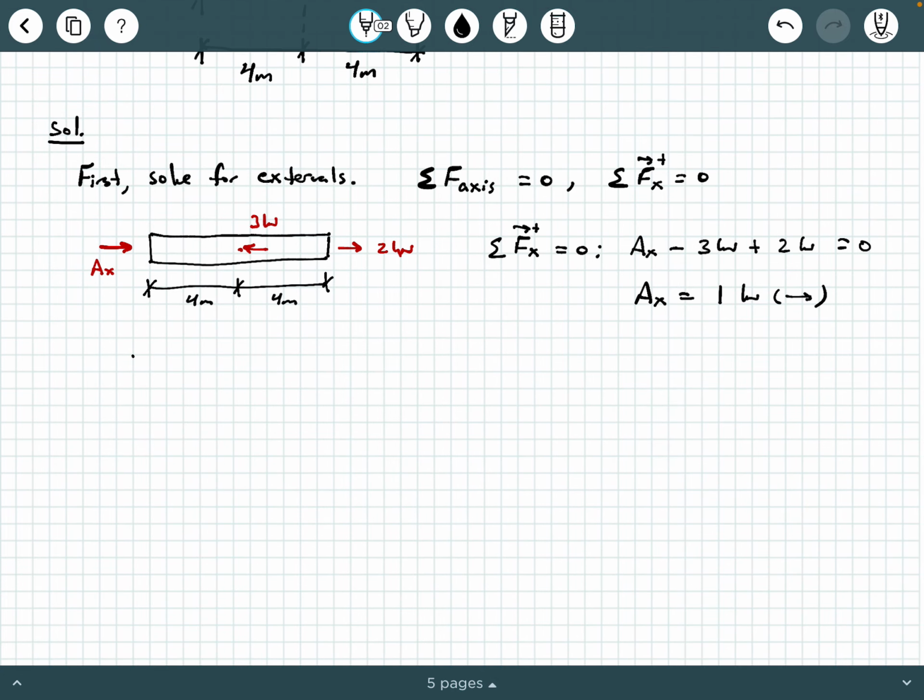Now we're ready to draw the axial force diagram. So if you remember, we're going to set up a set of axes. The vertical axis is going to be force, and the horizontal axis is going to be an x location. And what are our units? Well, the force units are kilonewtons, and the x units are in meters, okay? So what we're going to do here is we're going to put a sign convention with that force, okay? So up here on this axis, I'm going to say things pointing to the right are positive.